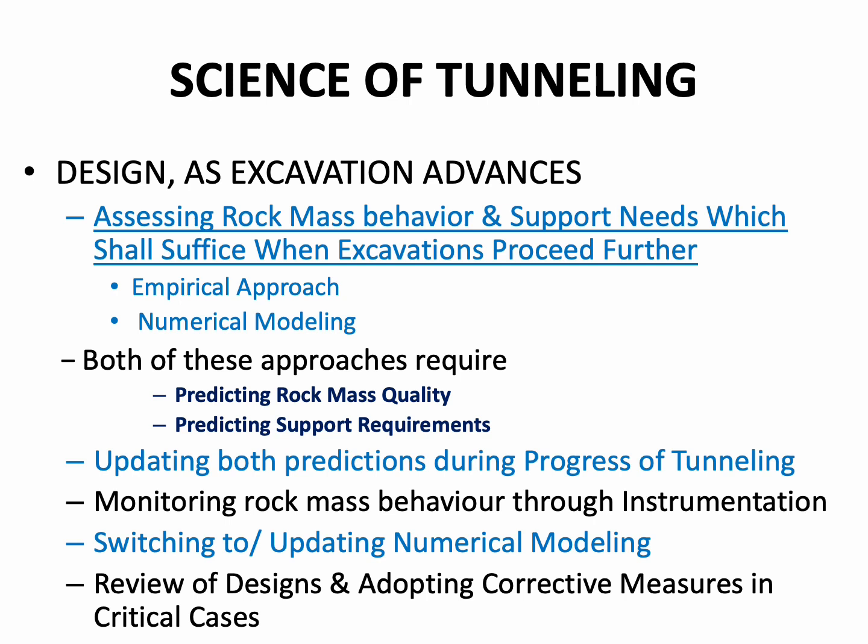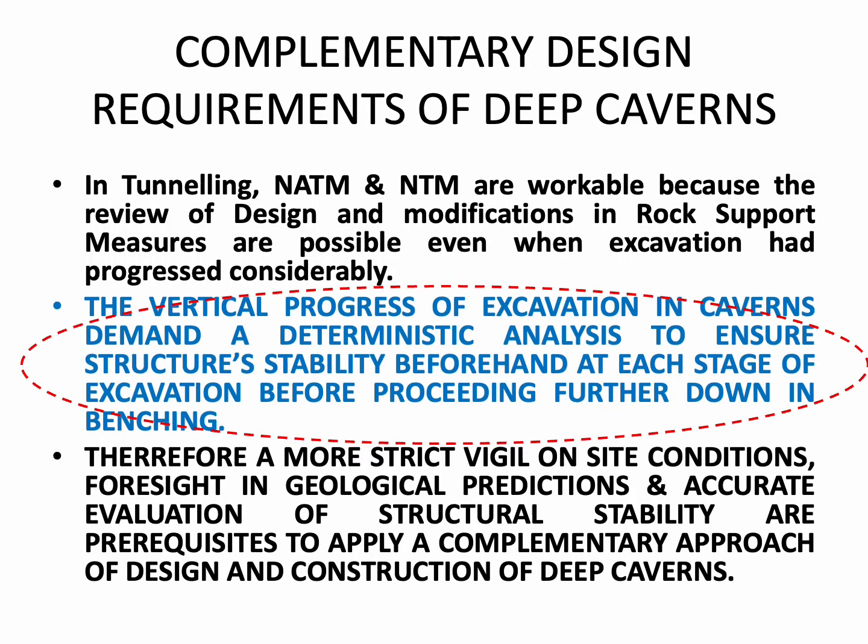Based on how the rock mass is behaving, one would need to switch to updating the numerical modeling, review of designs and adopting corrective measures in the critical cases. In critical cases, it would require change of design methodology and adopting corrective measures. The complementary design requirements of deep caverns thus are: